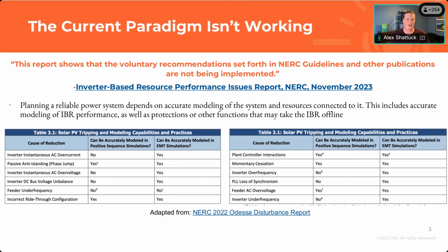We need a combination of both phasor domain and EMT simulations, doing maybe part of the interconnection process in the easier, faster phasor domain, doing more detailed work in the EMT domain, and knowing when and where to use those tools and how to use them is super important for a holistic, integrated modeling scheme.